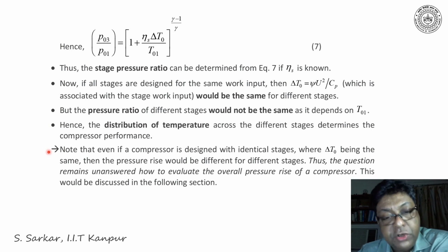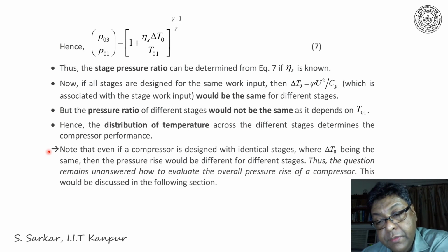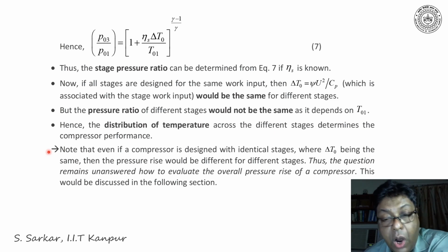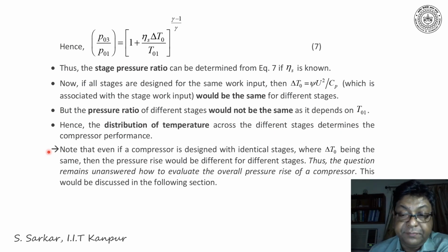Further, please note here that even if a compressor is designed with identical stages where ΔT0 is the same, then pressure rise would be different for different stages. Thus, the question remains unanswered how to evaluate the overall pressure rise of a compressor. This will be discussed in the next section.